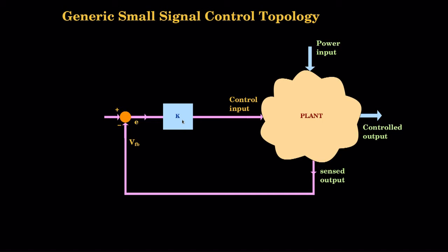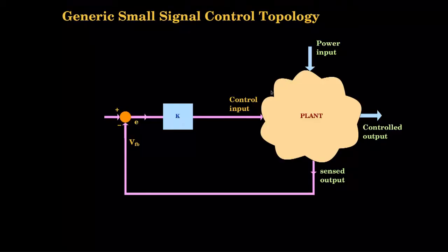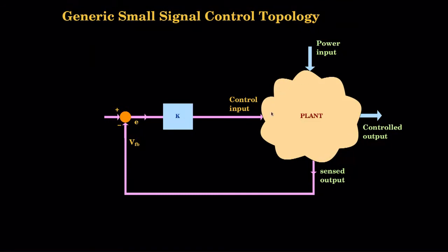That is one advantage of full state feedback, where K is like your proportional controller. In a proportional controller, you just put a gain, right? Like that, full state feedback, whatever may be the complexity of the plant, whatever may be the order of this plant, whatever may be the non-linearities, this will just be a pure gain, if it is a single input, single output.